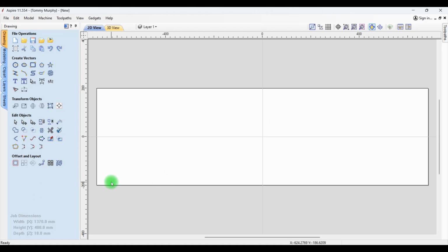Now I'm going to be concentrating on a section in the middle that's 1220 wide, which is the width of a 4-foot sheet of material. And because I'm going to be adding a little rebate to both edges of this that are going to be 6 millimeters, this is really going to be 388 millimeters. But I want to set out in this for 48 T-nuts in the center of this, and I will also be adding some grid lines to it.